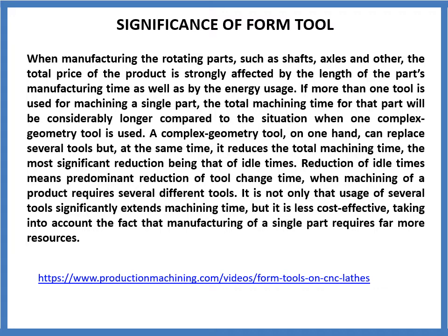A complex geometry tool can replace several tools, and at the same time it reduces the total machining time, the most significant reduction being that of idle times. Reduction of idle times means predominantly a reduction of tool change time.